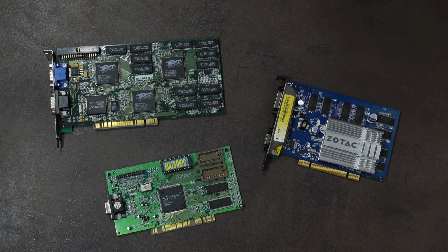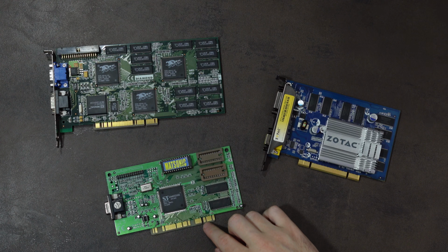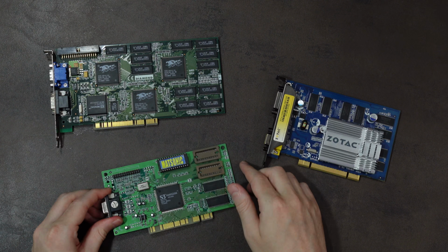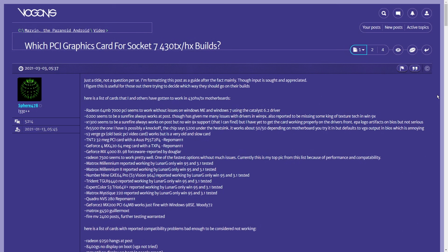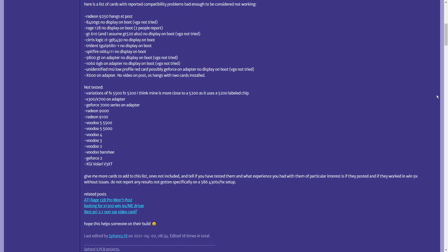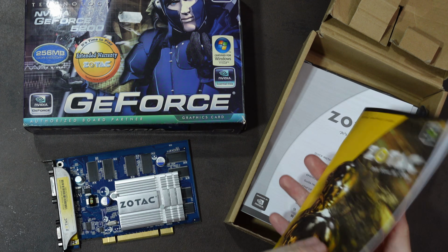If you want to be sure that the card works on 5V, you should only buy PCI cards that have a notch exclusively in the back, like this S3 Trio 64 V2DX from 1996. However, this limits the already small selection of newer cards quite a bit. If you want to buy cards with universal connectors, you will need to refer to experiences from other users of this specific model, as this is also probably not mentioned in the manual.